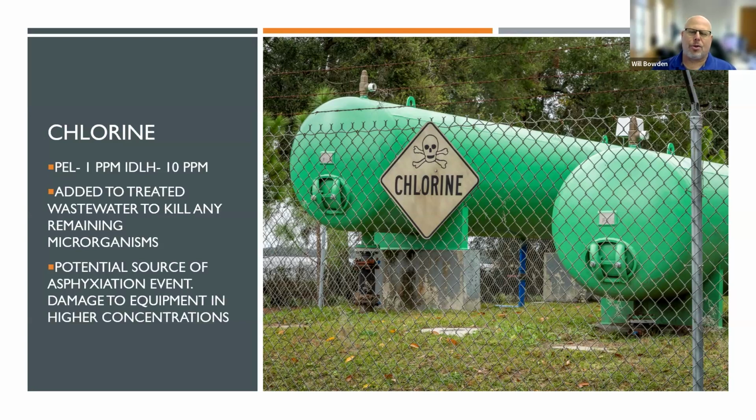Chlorine is a potential source of asphyxiation events for workers that are in the facility, but chlorine can also damage equipment in higher concentrations. Mixed with water, it can create hydrochloric acid, which is very corrosive and can corrode and degrade piping systems and other items within the facility.